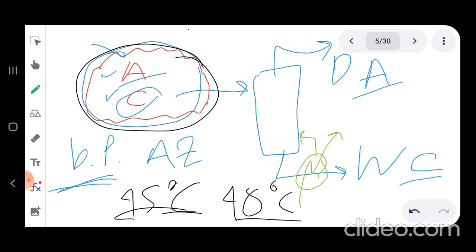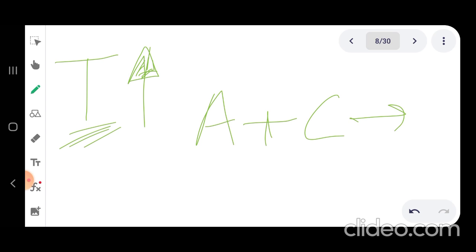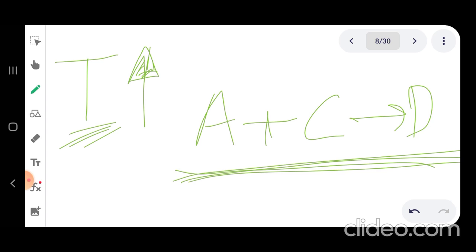What happens with some components, for example, let's say our components here in this example, A and C, is that at high temperature you initiate other chemical reactions. So for example, at this high temperature of the reboiler, A will react with C to form another component, I don't know, for example D, just as a name. And this reaction is only activated at this high temperature.